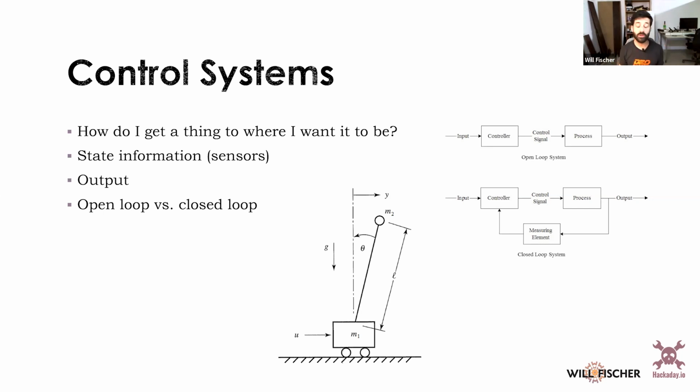So you need to start slowing down your motor effort before you get there. And there's a large amount of control systems out there that will do this. Some of them are very, very complicated and very efficient. Some of them are pretty darn efficient and not that complicated, like the PID controller, which is kind of like the bread and butter of your control systems. It was invented back in, I don't know, maybe the 30s or 40s. I'm not exactly sure. But it's still used today because it's so simple to implement. And so that's the one I would recommend to most people who are trying to do a control system. You can get more elegant than that. You can dive much deeper into control theory if you choose to.